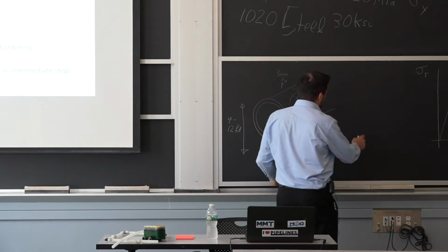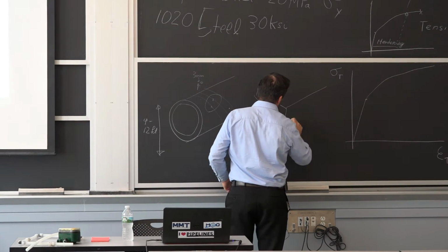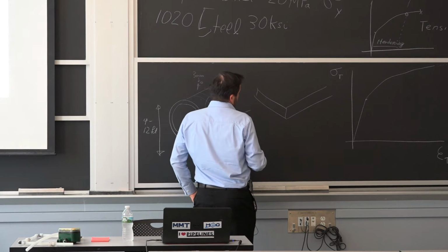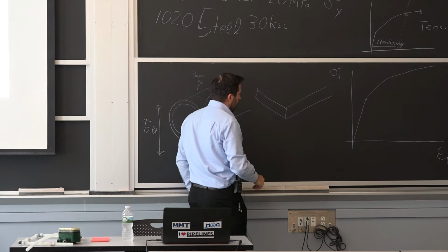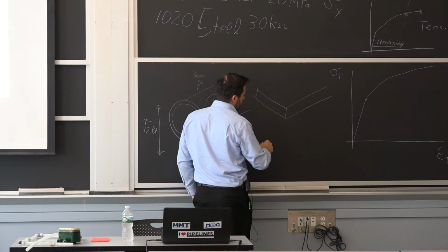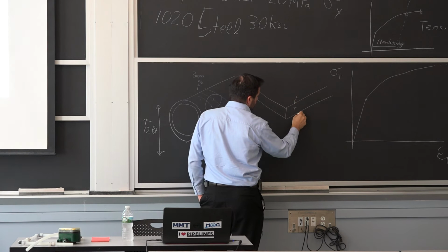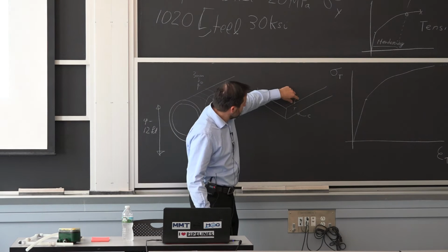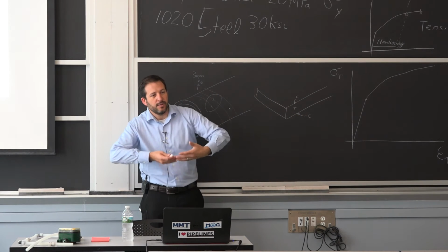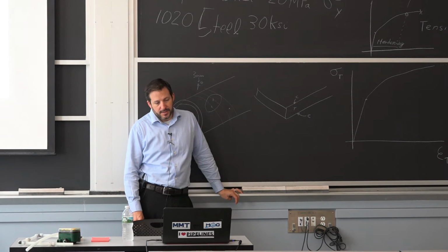So let's say we have just a standard plate that was cold formed. What happens, let's say, is it's always a little hotter in the center than on the surface. So when it cools, it's going to shrink a little more here. So you'll have tension in the mid wall, and then you get a little compression on the surfaces. So if I'm taking the compressive layer on one side, then all of a sudden it acts like a spring, and it's going to bend on me. It's a very significant effect.